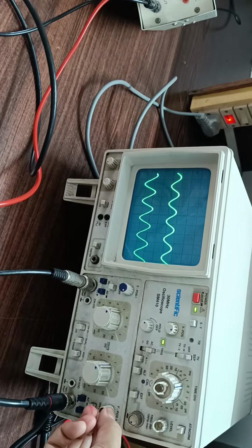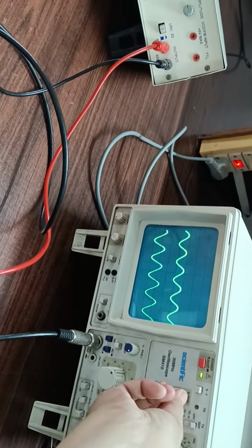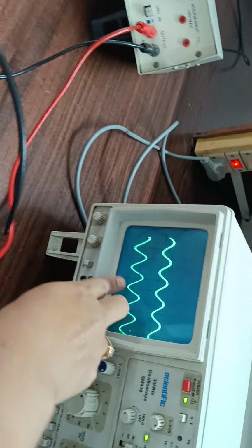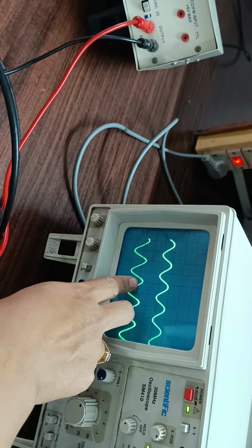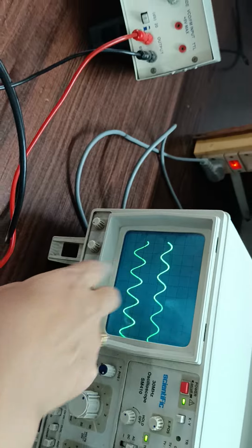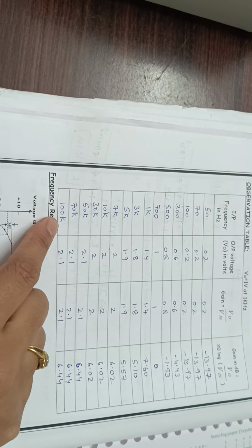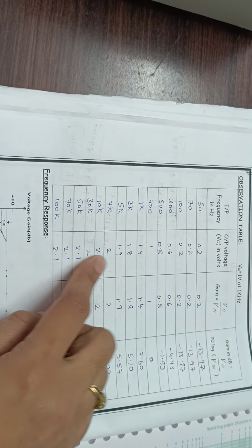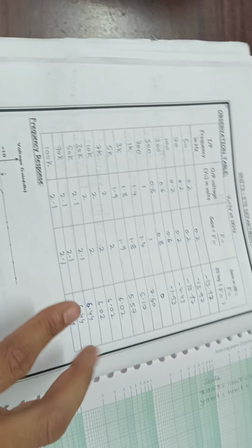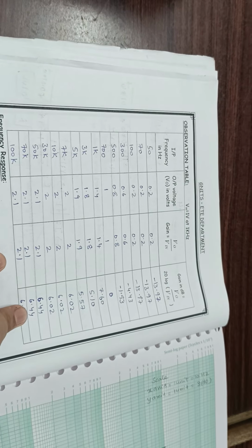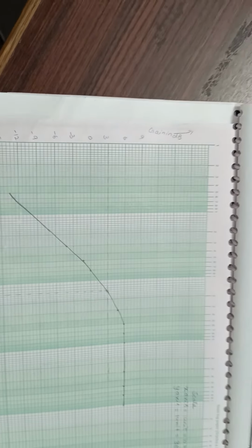Observe the output. You can see here output 1.4, here 1 into 2 more divisions, 1.2, 1.4. So you are getting output as 1.4. Then again take the response, start from 50 Hz to 1 megahertz and note down the values of V0 in CRO channel 2, and using calculator calculate these two columns and then draw the graph and identify the peak value